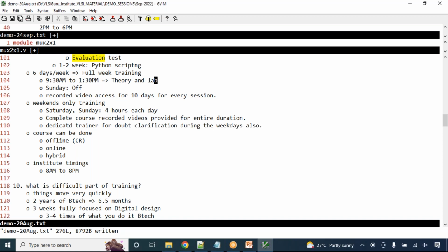The difference comes in the backend flow, majorly, where you do the floor plan, I mean physical design, the way you do DFT, custom layout. That is where things majorly differ. But as a design engineer, we don't need to bother about the backend process, right? As a design engineer, we don't need to worry. But when you go to the integration level, the difference will be there. See, if you are talking only about the design perspective, both ASIC and FPGA are the same.